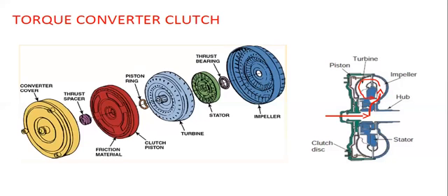So when the torque converter is not locked, that is, the clutch is disengaged, the fluid enters the converter and moves to the front side of the piston, keeping it away from the shell or cover. Fluid flow continues around the piston to the rear side and exits between the neck of the torque converter and the stator support.